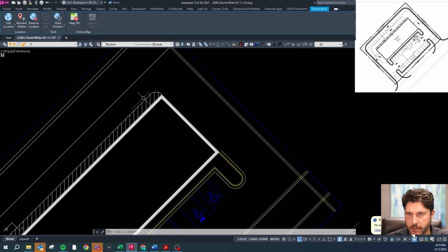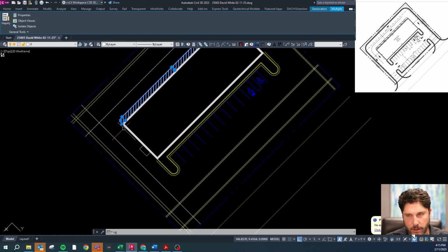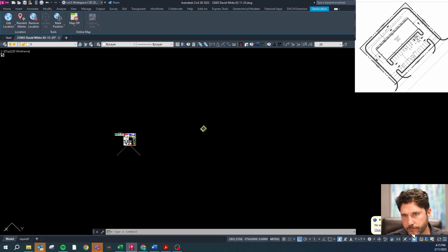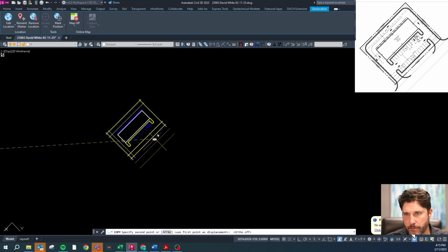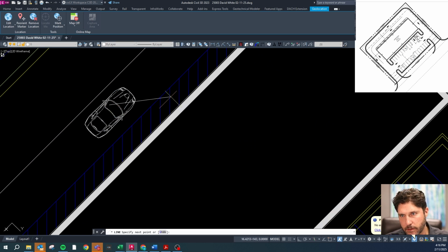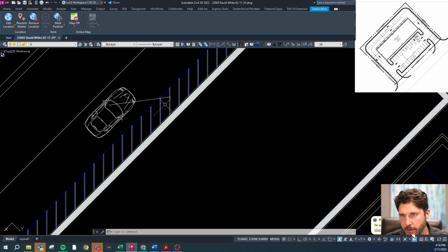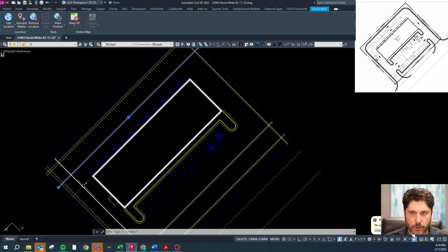And if your car is driving in this direction towards the top right of the page, and you select this line, this striping will show up correctly, where the view from the car is such that the lines are perpendicular to your path of view. So if the car is driving this way and they look over at the lines, they're perpendicular to where you're looking. So they're not trying to guide you down that way, they're blocking you from going that way. And that's the direction you always want that line work to be.